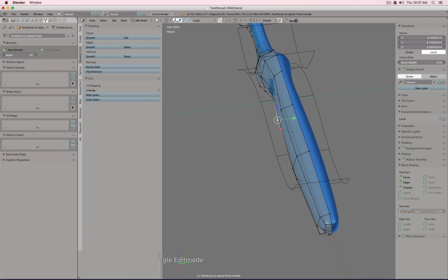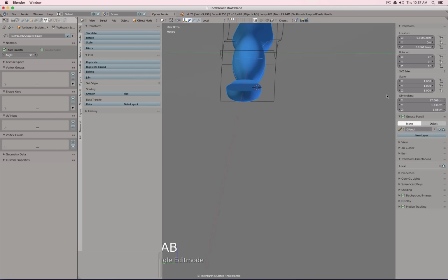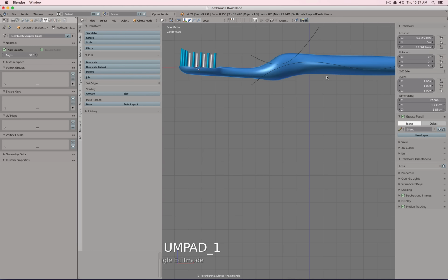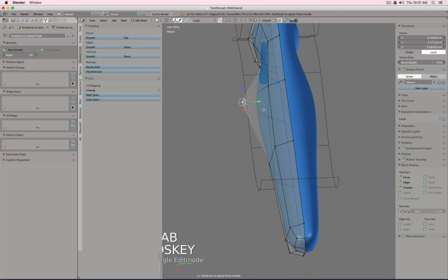Maybe let's move this one here to the side so it's better to see. So you see I make everything bigger, and there you can see how these two shells exactly fit. And again, that's the beauty of working with clones, because you can share geometry data between different objects. And then with the modifiers, we just split them. Blender does not have a split tool, for example, like Fusion. So in this case, unfortunately, we have to do this workaround with two clones and then just trim them. But in the end, same end result.